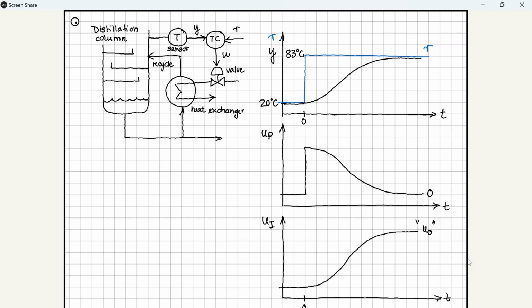We can see why it is important to integrate from 0 to t. This means we integrate from the time we switch the controller on until now. So if we run a continuous operation, it means that we integrate from 6 months ago until now. Of course, if the controller works well, the control error is very small for most of the time, and the controller output doesn't change very much.